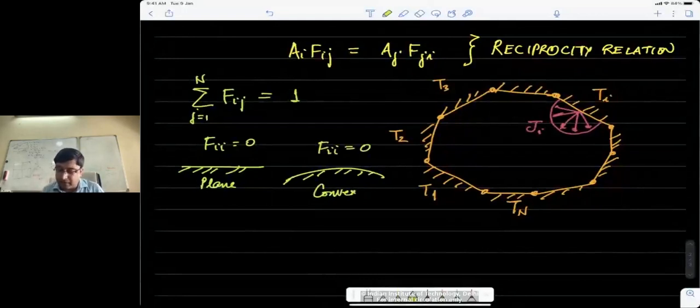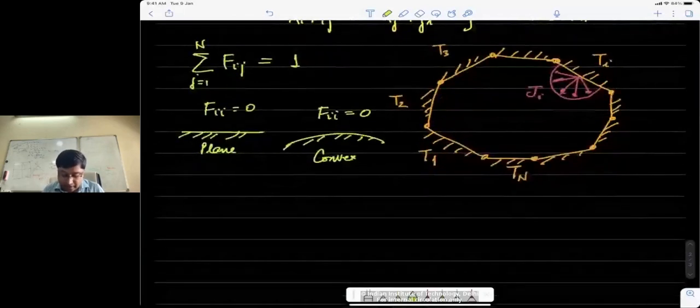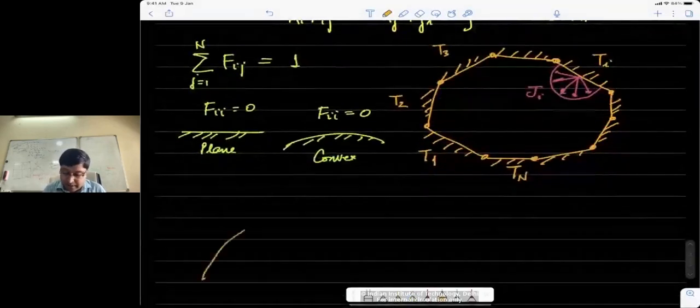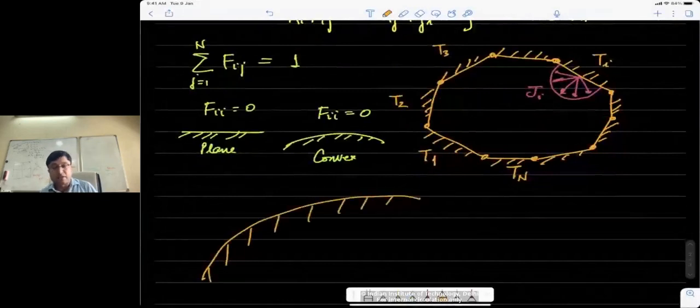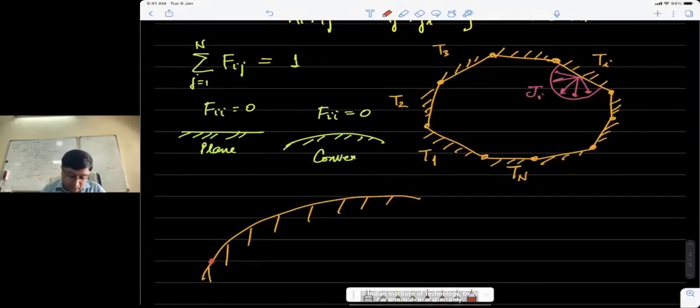The way I typically think of it in these problems, and I'll show you the trick, is this: if you have a surface, the way to say whether a surface will capture its own radiation or not is that you take a point on the surface, and join it with some other point on the surface, let's say this point.